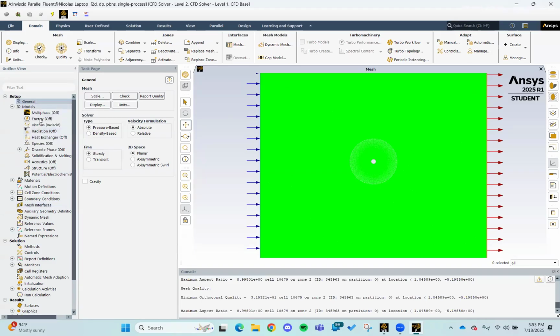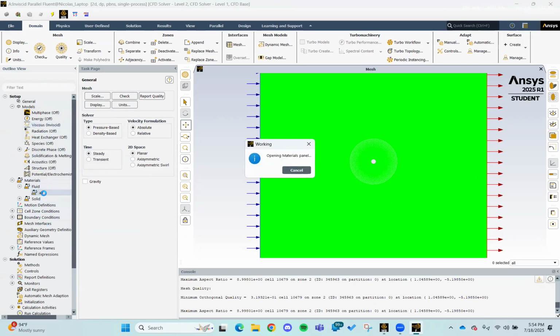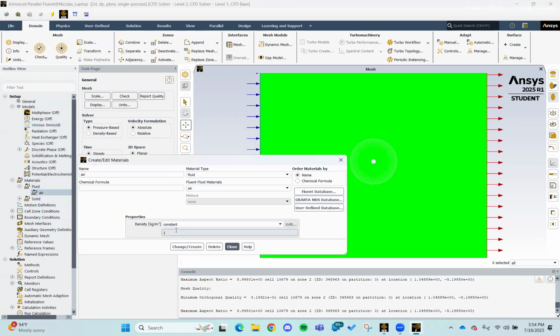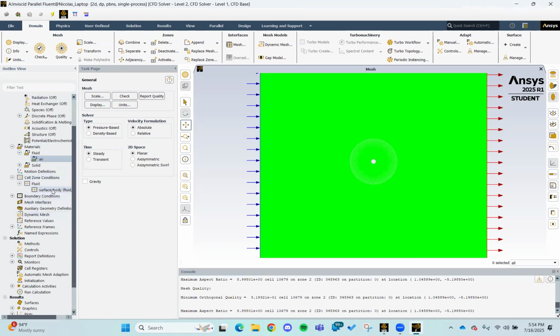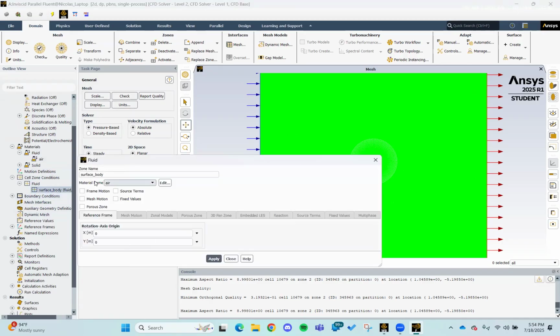First things first, I go to viscous and I select Inviscid. For this scenario, it's going to be Inviscid. Go to my materials there. It just shows up one as my density. For this case, I'm going to check over here. My stall zone conditions should all be good.